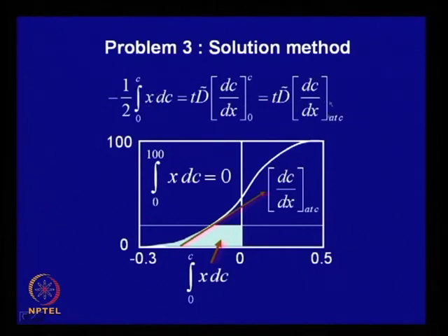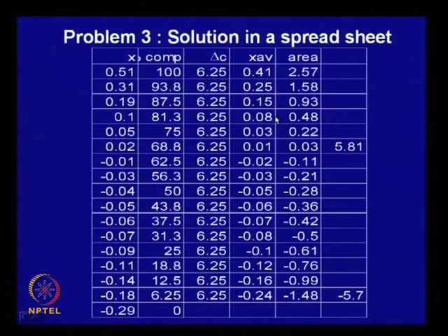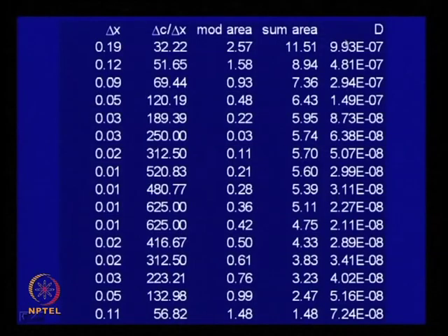The slope of the plot also has been determined, and the time t is given as 50 hours. So, substitute the time t as 50 hours, and therefore it is possible to calculate the interdiffusion coefficient as a function of distance or composition.